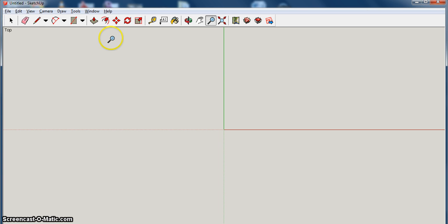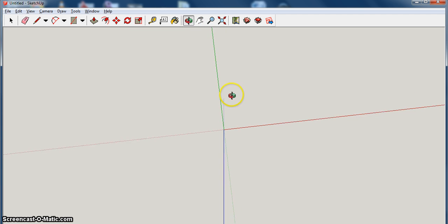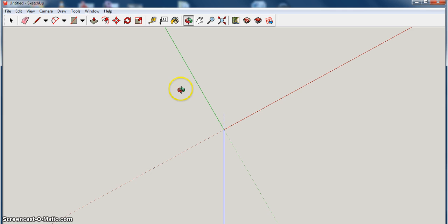Now it's quite important that, just use the zoom tool to zoom around a little bit, that from the start, when we draw a line, if we want to draw a line parallel to an axis, it'll change color. So whilst those ones are black, it'll click to the red, so I know that's parallel.